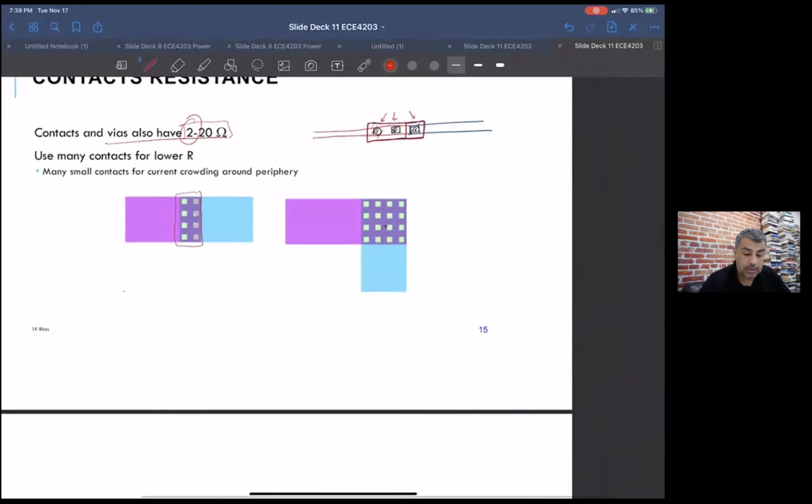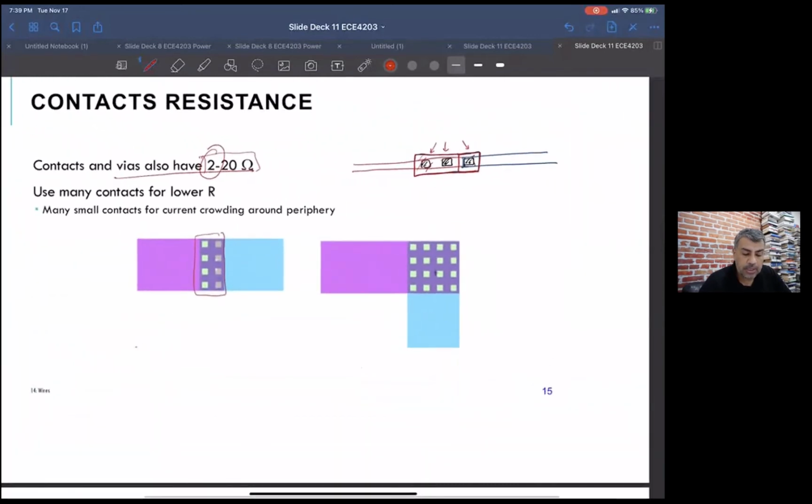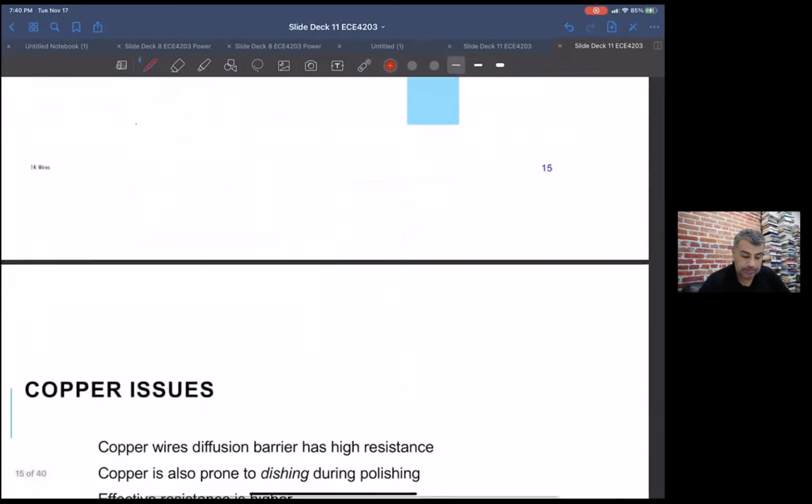It can dominate. Also, I think I might have mentioned this before, but vias and contacts are the lowest reliability thing in your chip design. It's not like there's a good chance that they'll go bad, but they have the highest chance of going bad, and there are so many of them on the chip. Whenever you can, you want to at least double up, and more, on vias and contacts from a resistance and a reliability point of view. Very important to do that.